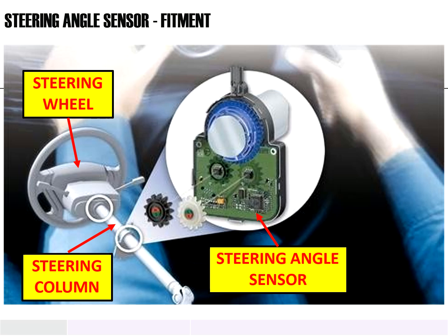In this lecture, we will cover steering angle sensor fitment, design and function, working principle, measuring principle, true power on or TPO functionality, Hall effect based steering position sensor advantages, Poka-Yoke connectors, sensor test standards, electrical protection circuits, and finally the steering position sensors summary. So let's begin.